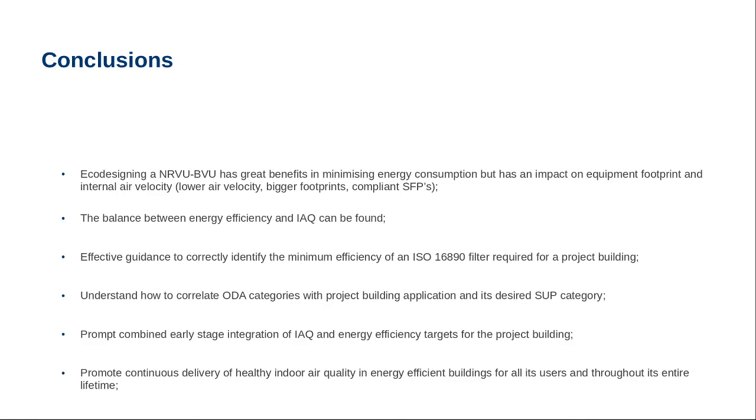Or even if I refer to an ePM1 at 75%, I understand that the media will be filtering dry pollutants so small that they can be absorbed by the bloodstream, and these are suspended particles smaller or up to 1 micron in size, and the media will be working at an efficiency level of 75%.